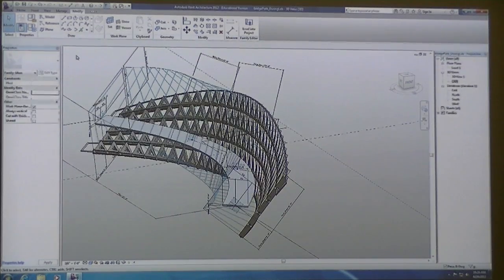And I would recommend always using the rectangular pattern and then creating whatever you want. When you get into those other shapes and you get a lot more adaptive points, it gets a lot more complicated, especially when you start to apply it to a curving, complex surface, and you run into a lot more errors. So if you can make whatever you would like out of a structure that's in that rectangular format, you're always probably going to do pretty well.